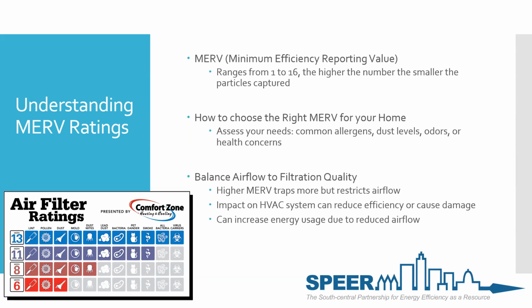And if it's got restriction, it's now producing more heat, heating up the bearings as it turns because you don't have enough airflow going through it. The fan is trying too hard, in a sense. And so it's going to shorten the life of the blower motor. So the higher the filter rating, you've got a problem with it. If it's pulling out too many particles, it will get dirty much faster and have to be changed at much shorter intervals.